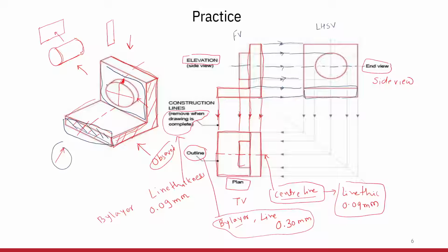Then after drawing this, we see that there is a rectangular portion above this, immediately following this portion. So how do we get that? This is the boundary, right? So within these boundaries, we will be drawing this vertical portion. As we know, the width of this portion and the width of this portion are exactly the same. So we draw these vertical lines between these projectors and correct it, to complete this outer portion.